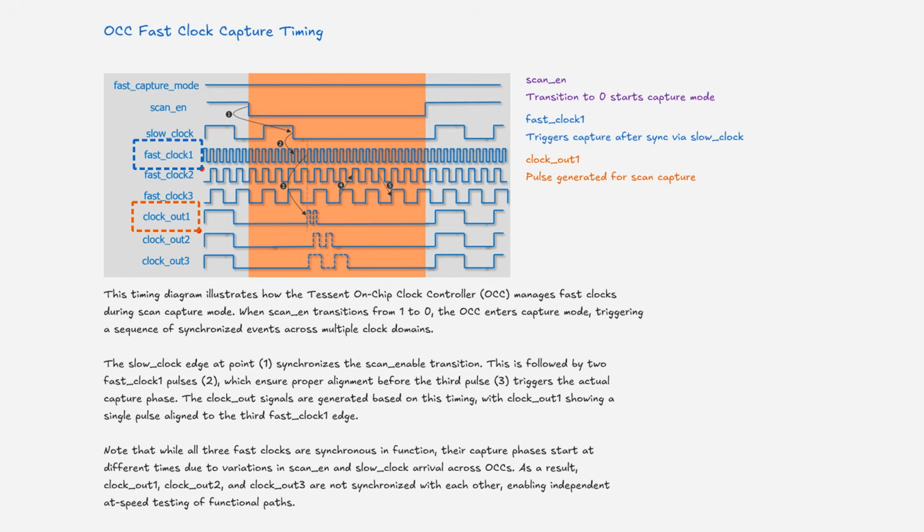Note that while all 3 fast clocks are synchronous in function, their capture phases start at different times due to variations in scan enable and slow clock arrival across on-chip clocks.